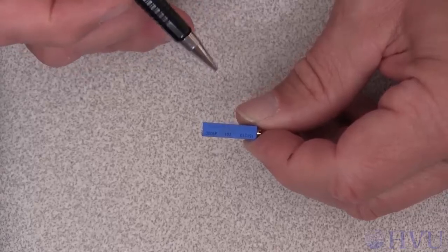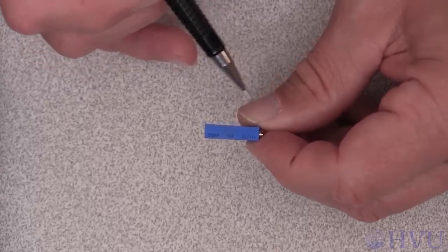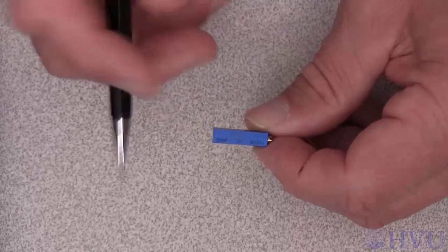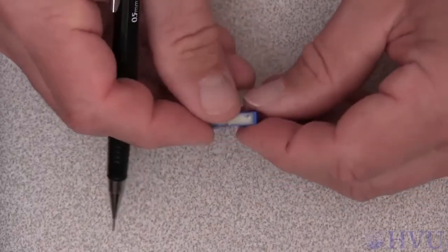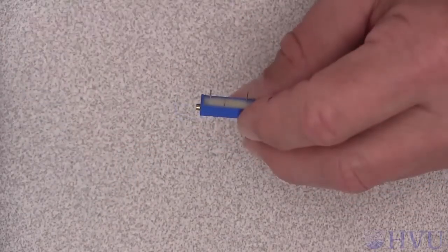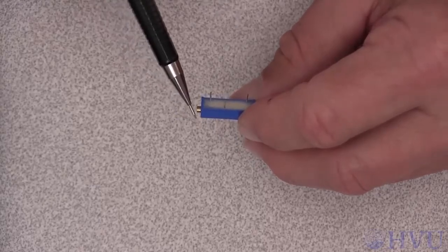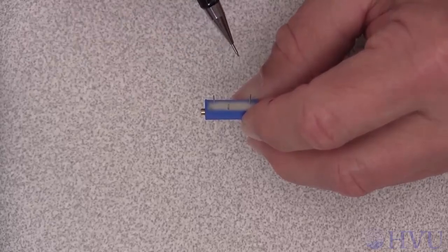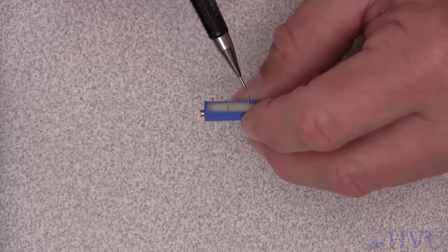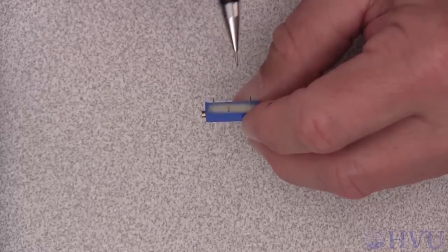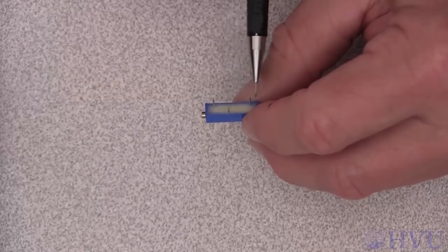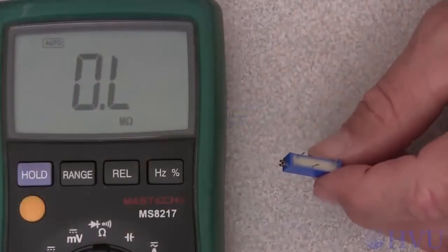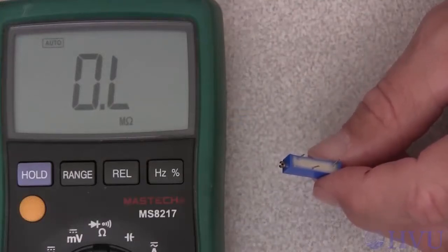The actual resistance of the potentiometer can be adjusted to any value between about 0 and that maximum resistance by turning the set screw on the end of the pot. The potentiometer has 3 terminals with which to connect it to your circuits. The resistance between the 2 outer pins is simply the maximum resistance of the pot. The resistance between these pins does not change as you turn the set screw. The resistance between the center pin and either of the 2 other pins does change as you turn the set screw. Since this is a variable resistor, we can't tell what the actual resistance is without measuring it.